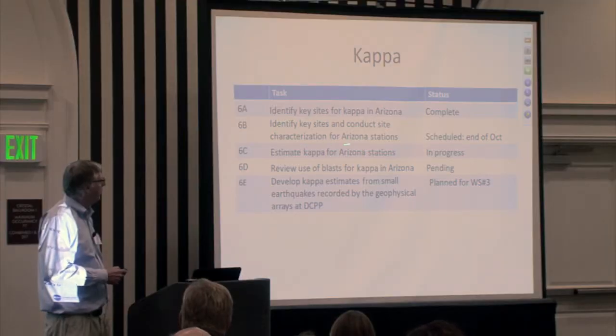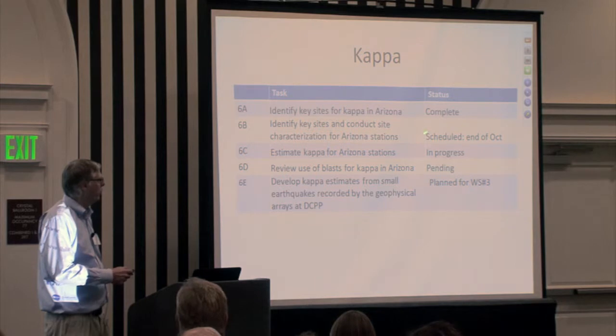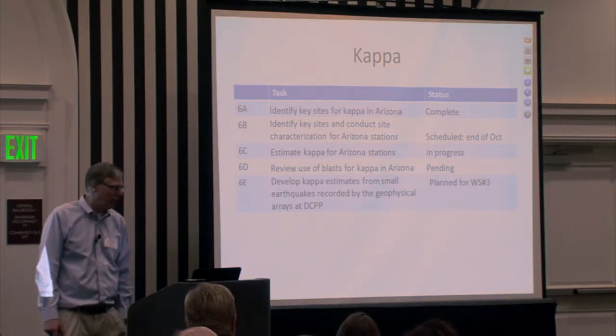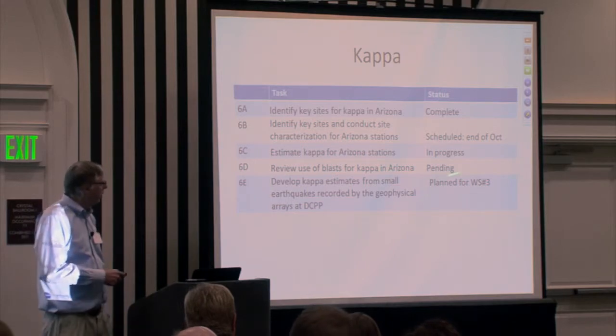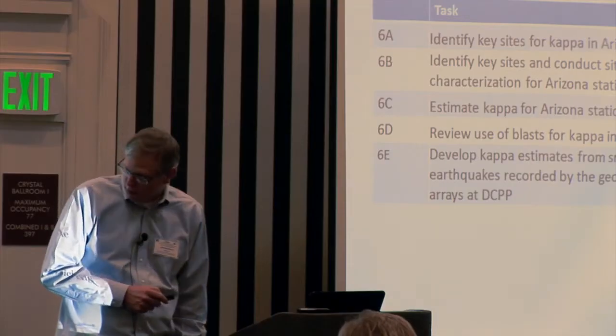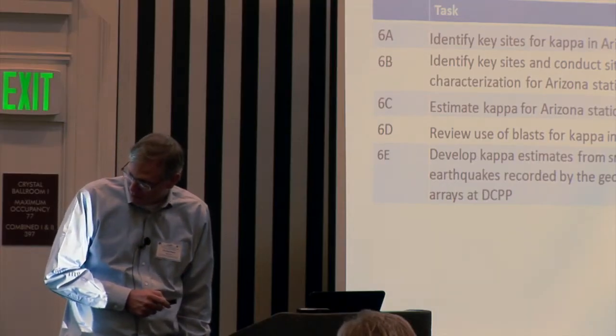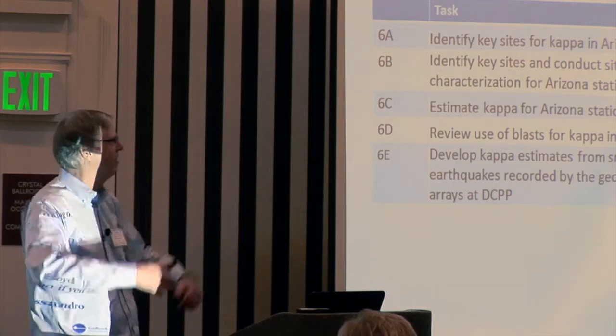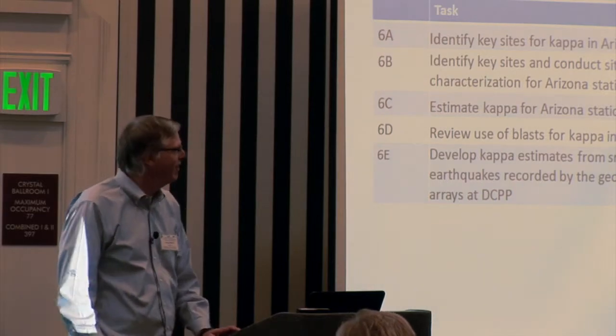Then we got those sites and conducted the site characterization. So that work has been scheduled. Rob Kane is out running SASW at those sites, so we'll have a shear wave profile scheduled for the end of October, broadly envisioned as the end of October into November.